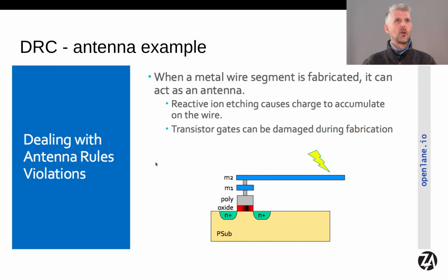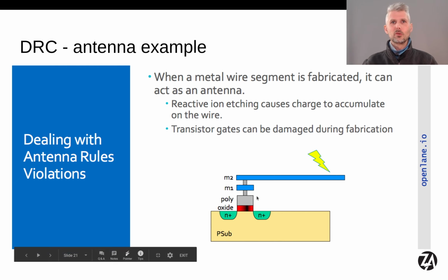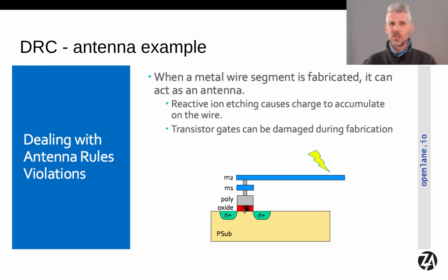Here's an example of a DRC rule. In my Hackaday talk, I said it was my favorite one because I thought it was a really cool one, but actually now having gone through the process, it was one of the most annoying ones because they were difficult to get rid of. But when we built our gate, which is sensitive to electrostatic shocks, it can be destroyed with a high enough voltage, and we've built up these interconnected layers, if we end up with a long enough wire, we basically made an antenna connected to this sensitive gate.